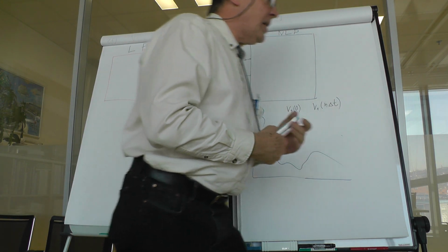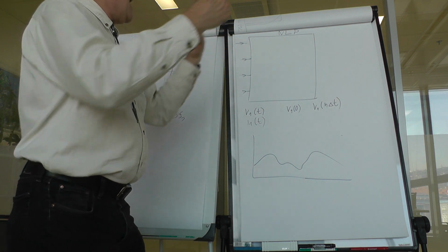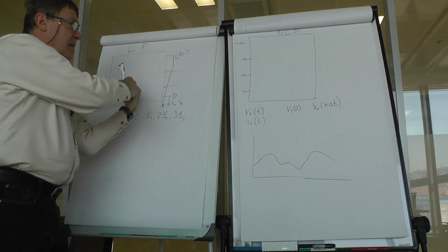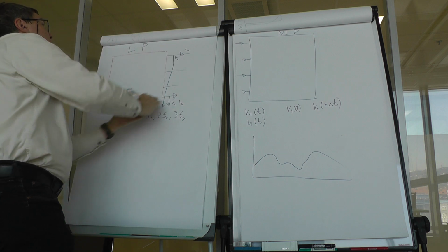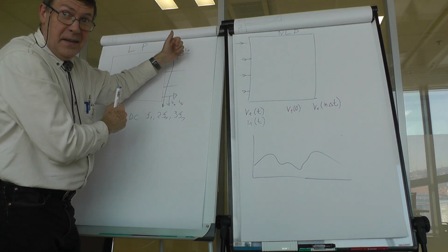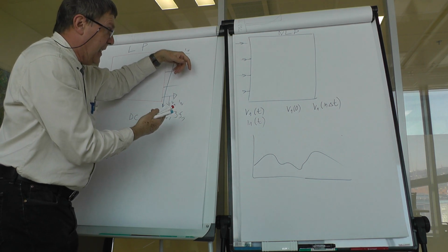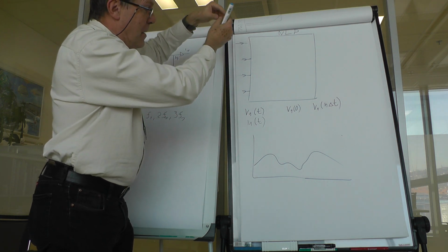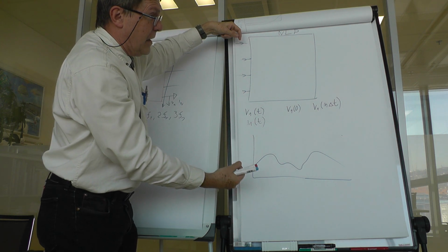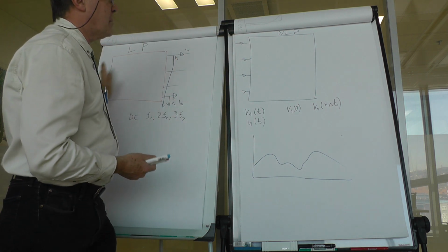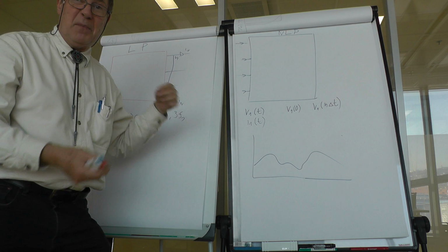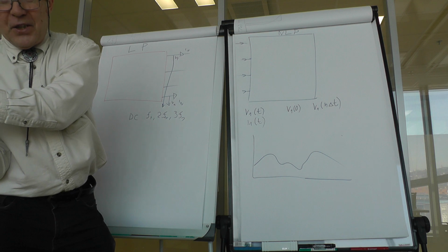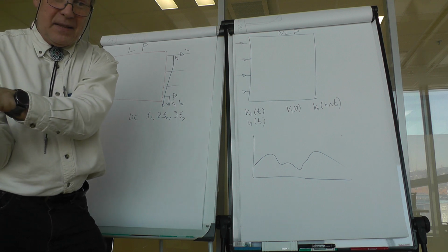After running this analysis, I can transform the solution to the frequency domain and put it through the linear circuit. I have some resulting behavior in the frequency domain. I transform it, and I must get what I have started with. So the full loop must be in balance. All harmonic components must be so balanced that the voltages in the time domain and the voltages in the frequency domain are balanced.